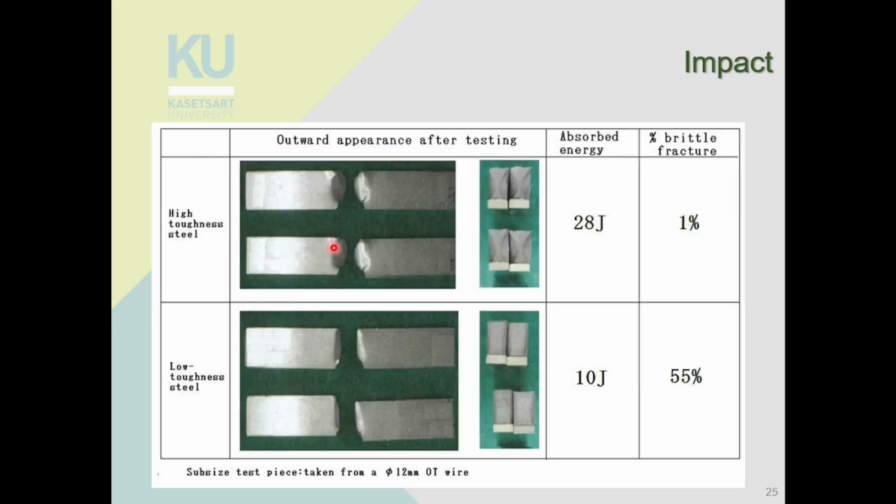And you can see the specimen is rougher. The fracture surface is not flat, and the surface itself is quite rough. You have a lot of dimples compared to this picture here, which is flat.